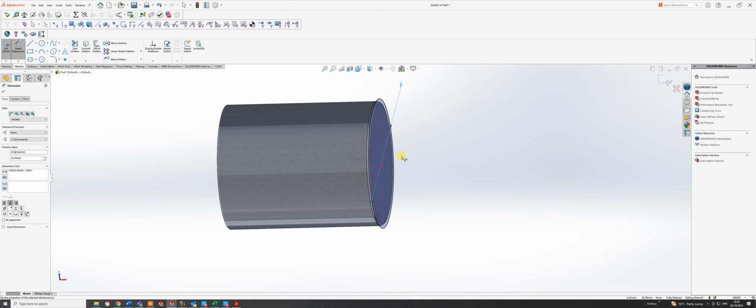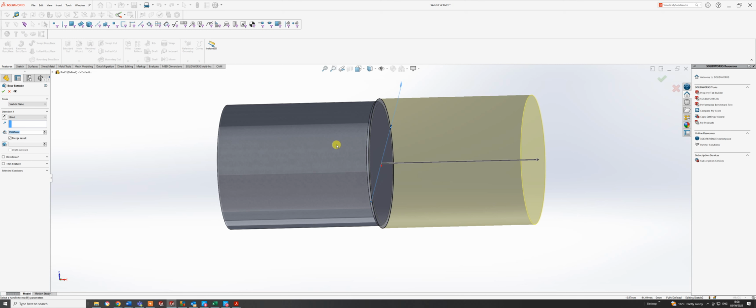So the first stage I'm going to extrude because the gearbox, when you take it to bits, not that you will, is actually in 3 parts. So the first part, I'm going to go to my features menu. I'm going to go extrude boss base, and as you'll see on the drawing, it is actually 4.8.